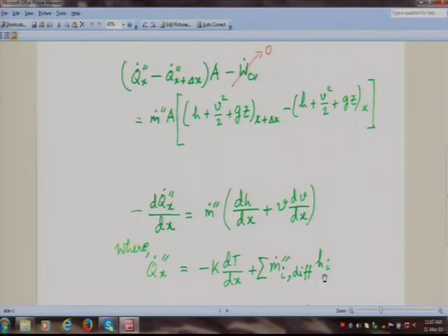Okay, so this is familiar to us. Again, we had done this first time, I think, when we were doing the well stirred reactor. At that point of time, we wrote diffusive mass fluxes for the ith species. For the well stirred reactor, of course, remember that we said that the mixing is so good that we could neglect the diffusional fluxes, but in general we have to keep diffusional mass fluxes. Now, compared to the bulk flow, individual species have individual mass fluxes, diffusional mass fluxes.